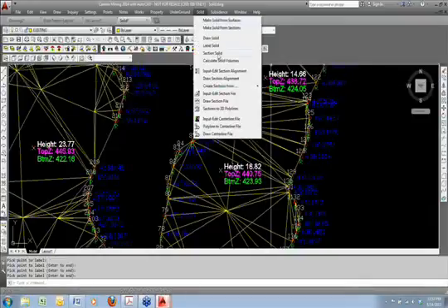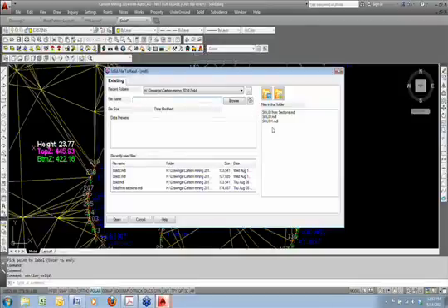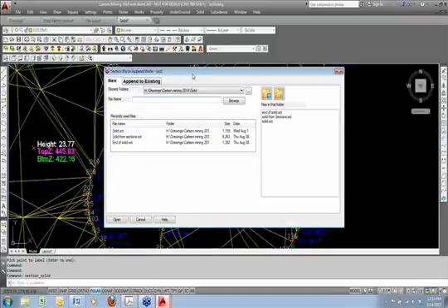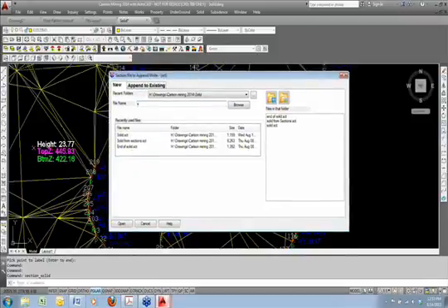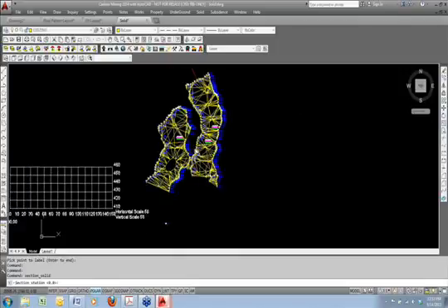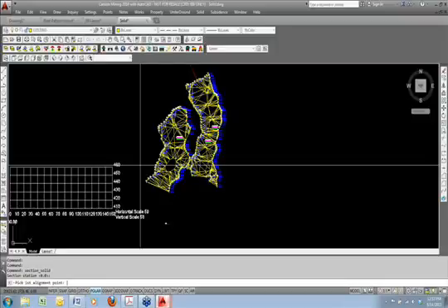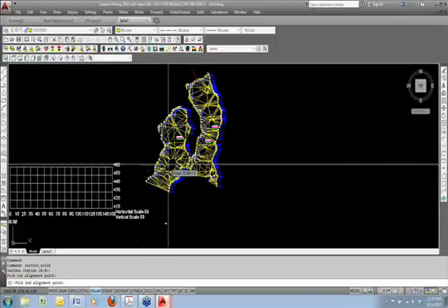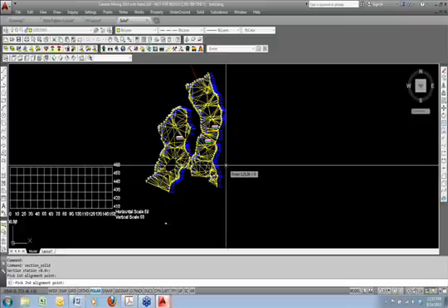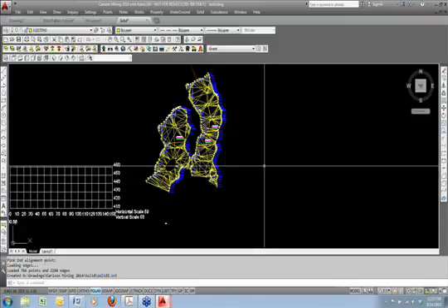And then I want to cross-section it. So now that you've got this solid created, I can do section solid. And let's grab this new one called solid 2. And it's going to make a section file, SCT file, and we'll call it solid 2 to match. Station 0. So you could do this multiple times and just do a continuous cross-section file all the way down. We'll just start at station 0. My first point will be here, and I'll go across that opening and then back over to the right. So it made a cross-section that you see at the bottom, SCT file.